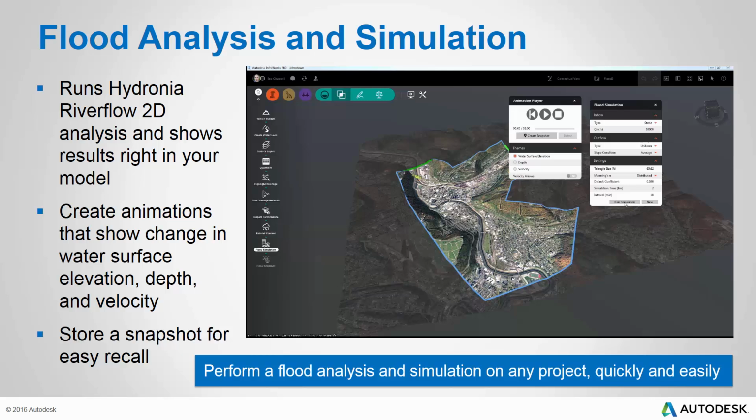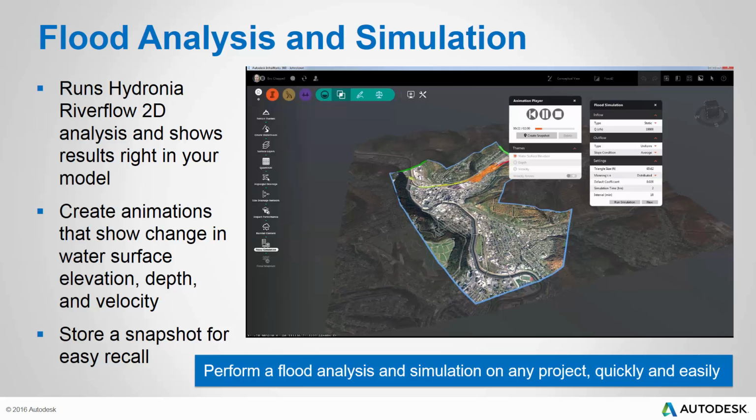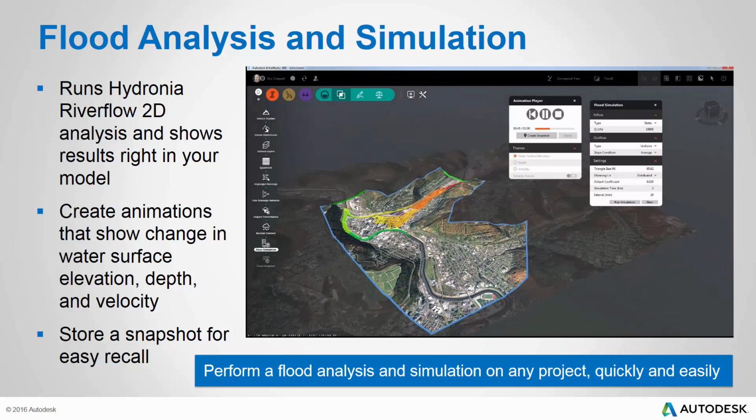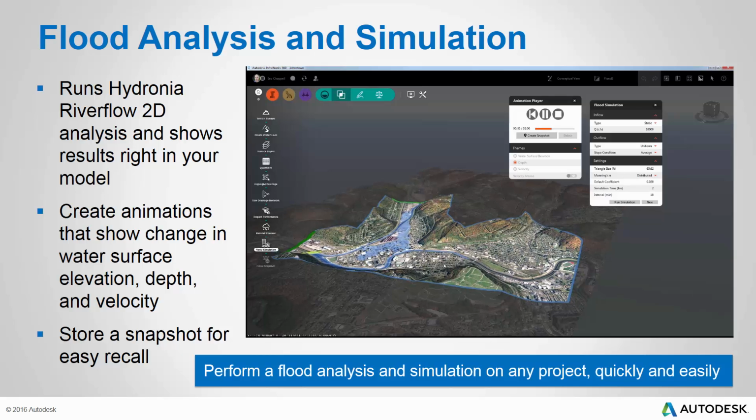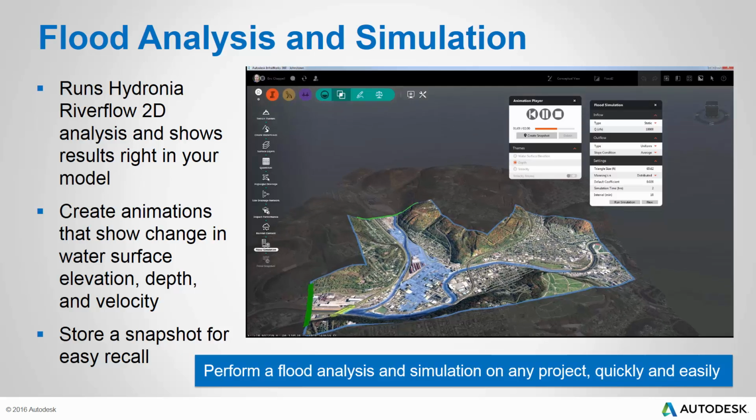and once the simulation is complete, I can play the simulation in the model, analyzing water surface elevation, depth, or velocity. Here we see a very visual and easy to understand animation of the change in water surface elevation over the 2-hour period, and then again with depth. And that's the beauty of this tool, how easy it makes it to communicate the flood analysis results to others.